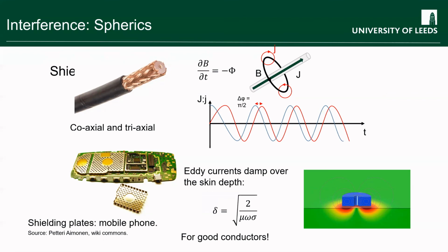And in order to avoid inductive coupling from magnetic fields, you also put in layers of soft magnetic material, so that any magnetic field is essentially confined to your soft magnetic layer. Preferentially the magnetic field will go through the soft magnetic layer and not through the inside of your room, and so the room is very, very quiet, even from inductive pickup from mains fields.